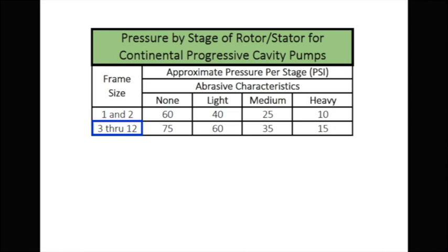So what we're going to do is go over to the right, and there are no abrasive characteristics in there. You can see that we can pump up to 75 PSI. Now if we slide all the way over to heavy again, you will notice it goes from 75 PSI to 15 PSI. So once again, it's very important to understand that when you're applying that to your application.